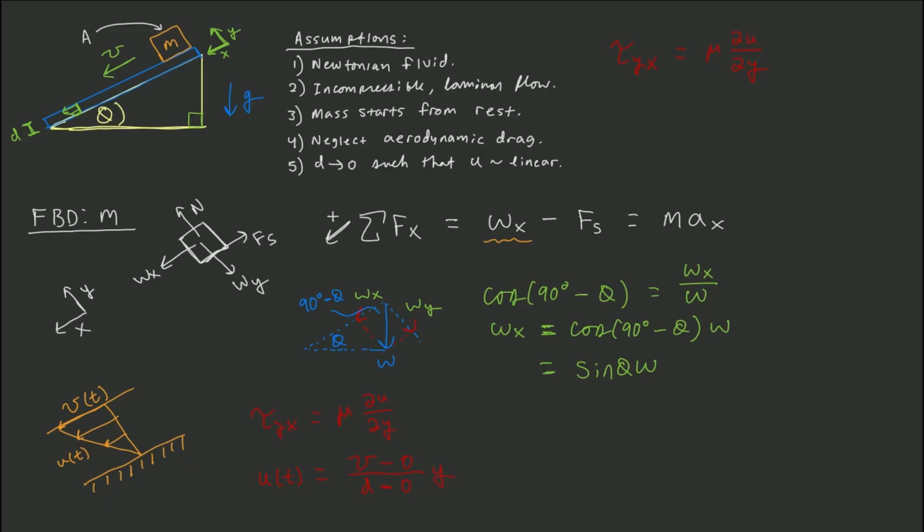So that's the slope of our velocity curve, of our velocity function. And then we just multiply that by y. So why does that work? So big U over d times y. You can see that at y equals 0, this function is 0, as it should be, because y is in this direction. So at y equals 0, our velocity little u is 0.